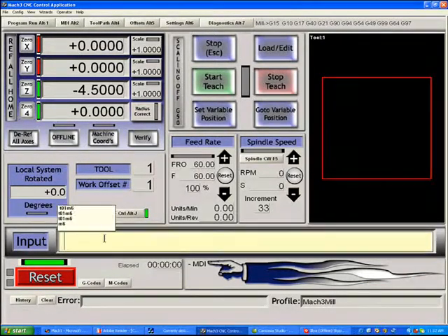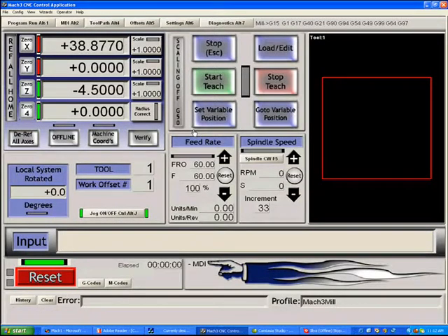From this point forward, M666 becomes a valid G-code command. And when we enter it, we will move at feed rate to 50, 50, and whatever the number was that we put into the Z. And as you can see, the X moves first because that was our first movement line. You can see it's moving very slowly. That's because we told it to move at feed rate. Let's stop the move by pressing the escape key on the keyboard and then raising our feed rate to 500.